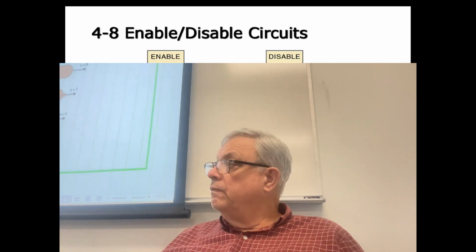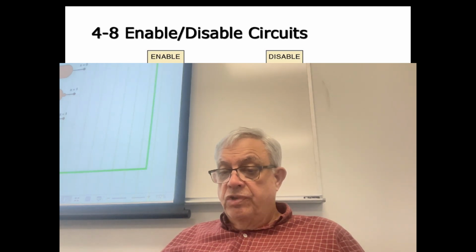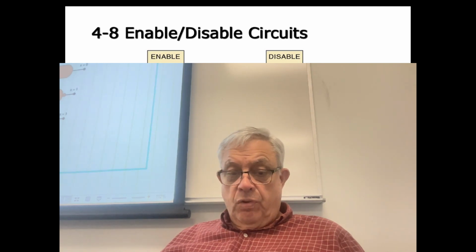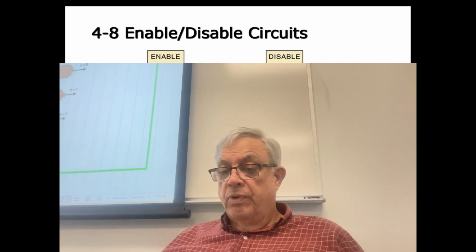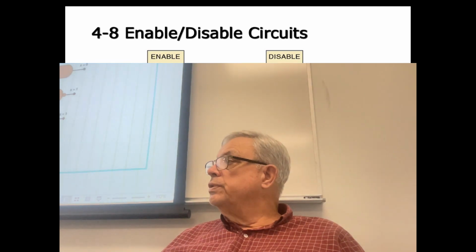Doesn't matter what's at A. In this case, if B's a 1, then the output's a 0. And again, it doesn't matter what's at A. So if I put the pairs together, B's a 0, then the NOR gate's going to give me an inverted output. If B's a 1, I block it. These are great digital switches.